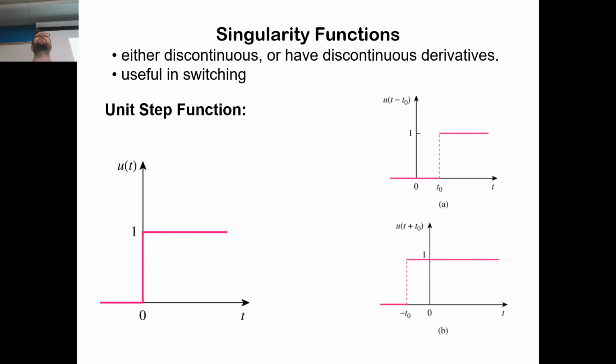The unit step function just simulates a switching event. Something is zero before some time, and it's non-zero after that time. It being a unit step function means it has a magnitude of 1. So you can multiply it by anything. Say I want to represent turning on a voltage source equal to 25 volts at t equals 0. We'll just say 25 u of t, like that.